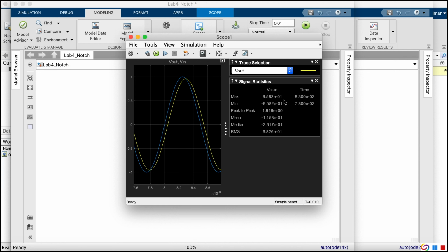And that's another point on the graph that you need to make. So you need to make a graph that is between 10 hertz to 10 kilohertz, and you just perform these tests and collect this AC peak amplitude of the output voltage for each frequency, and then connect those dots to complete your plot. And the points that you need to collect the data samples from are given in your lab instructions as well.